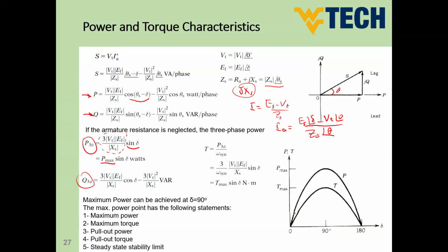So if you draw the curve of the power, this would be the shape of the curve. And I'm going to consider only the angle from 0 to 180 degrees. And we will discuss more in depth about the angle. We cannot go beyond 90 degrees. We will discuss the reason for that. So the curve here, you can see, is the power versus the power angle, delta.